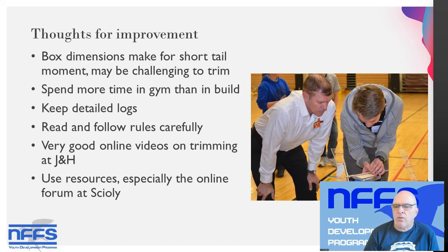Once you get the plane starting to fly, you're going to want to make very small adjustments to either the wing incidence or the center of gravity, moving the clay on the plane. Very small adjustments will make a big change because this is a challenging plane to trim. They will fly well once you get them trimmed.